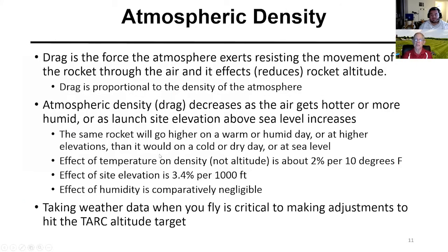Atmospheric density. Drag slows your rocket down, and eventually drag and gravity consume the energy that the rocket motor added to the rocket. And drag is proportional to the density of the atmosphere times the square of the velocity of the rocket. But the density of the atmosphere changes. It is less when the air is warm. It is less if your launch site elevation is above sea level.